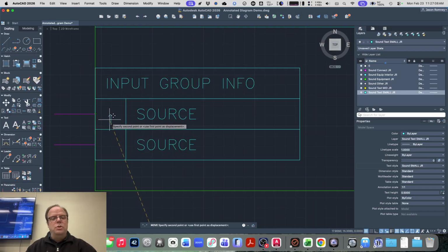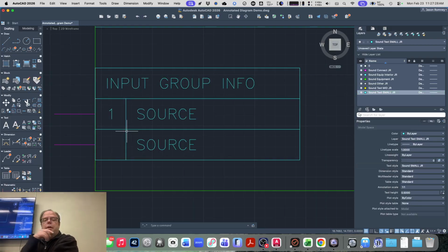So I'm going to make myself a little guideline between these two midpoints that will give me something to snap to. Then I stick it there, and I can just delete that line. Now I know it's going to be perfectly centered, and anytime I change it, it'll just grow out from that center point, center mid.